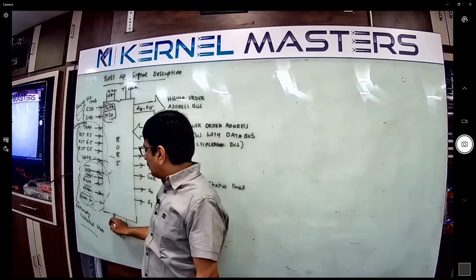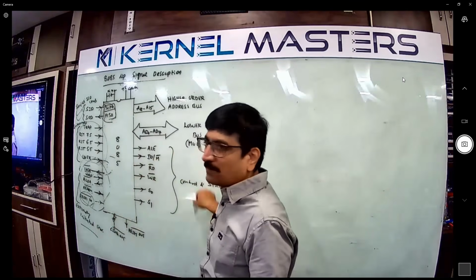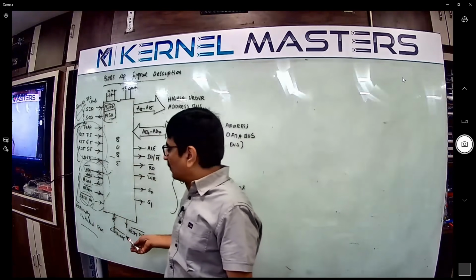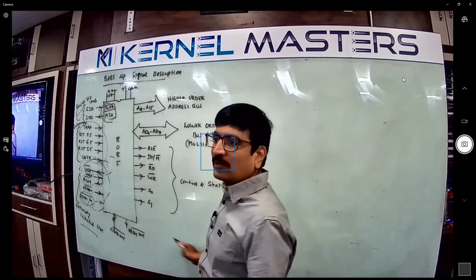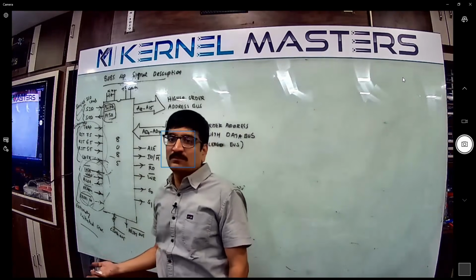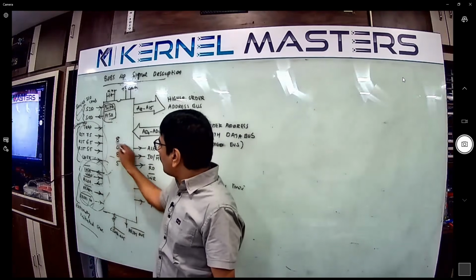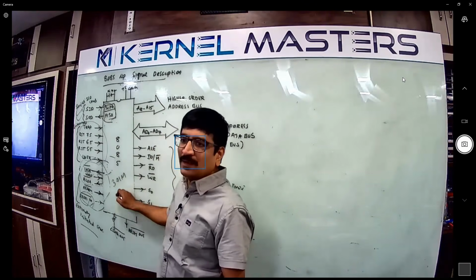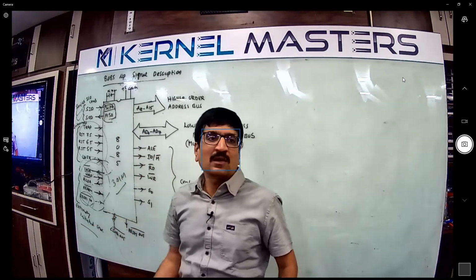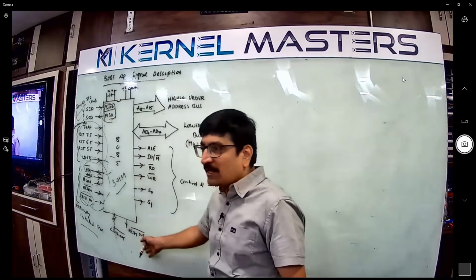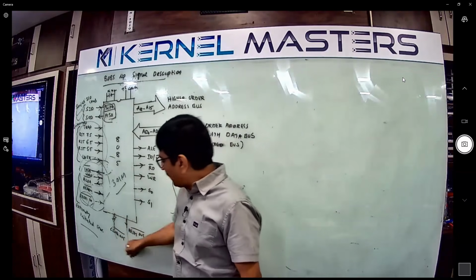Clock Out. What is the meaning of clock out? Surrounding the microprocessor there are many peripheral supporting ICs, for example UART, I2C, timer, keyboard controller. Those are all digital circuits and need a clock also. So the microprocessor generates the clock as an output; the microprocessor has an onboard clock of 3.01 MHz. Anybody who requires a clock among the surrounding chips is provided one through Clock Out. Reset Out is also an output, for the many surrounding chips.